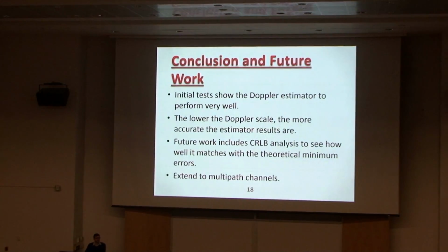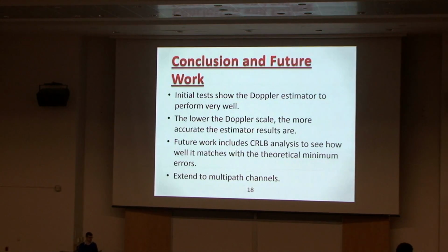How do you expect the signal-to-noise ratio of your channel noise to relate to the variance of your Doppler estimate? The signal-to-noise ratio is directly related. The Cramér-Rao bound depends on my SNR, because what we do is compute the Fisher information matrix to get the Cramér-Rao bound. The Fisher information matrix itself is inversely proportional to the noise variance, from which you get the SNR. The Cramér-Rao bound is inversely proportional to the Fisher information, which means it is directly proportional to the noise variance. So once I know the SNR and the remaining parameters for my Fisher information, I can get the bound.